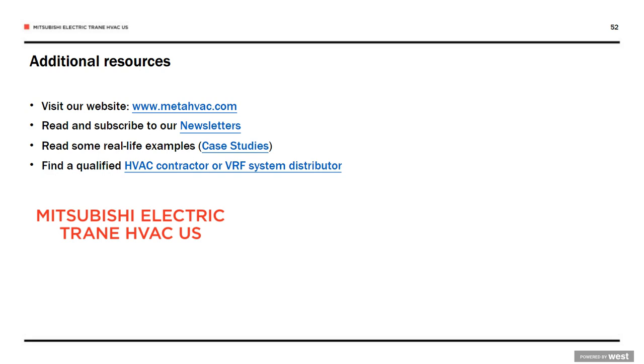If you can provide the cooling with cool outside air, that DOAS system is going to be set up to bring a certain amount of air into the building. And if it doesn't have to work very hard to do it, it makes a whole lot of sense to try to cool, say, the building with DOAS and then trim it out with the VRF system.